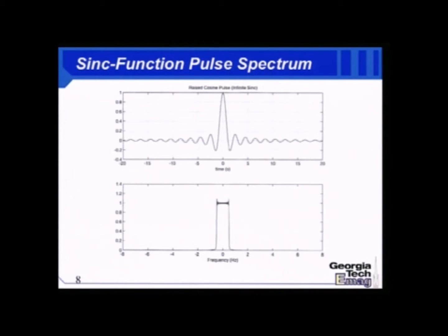And that's an artifact of the fact that I don't have an entire sinc pulse. I only have plus or minus 20 cycles of a sinc pulse. I had to truncate it at some point to get it to fit into MATLAB. And so a realistic truncation like this produces a little bit of ringing, and then, again, infinite support outside of the box. But it looks kind of like a box, so at least we know the behavior is appropriate.